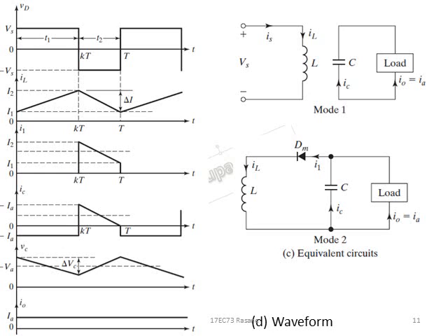So let us look at the waveforms here. This is the on time, when the chopper is on, and this is the off time, when the chopper is off. Here we are seeing the inductor current during mode 1, T1. When the chopper is on, the supply voltage gets connected to the inductor in this fashion, and the current is flowing from top to bottom through the inductor. The direction of the current arrow is like this, and hence the current is shown as rising and positive from I1 to I2.